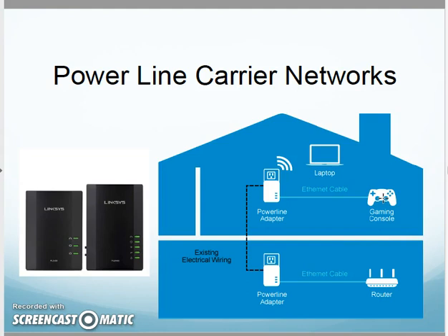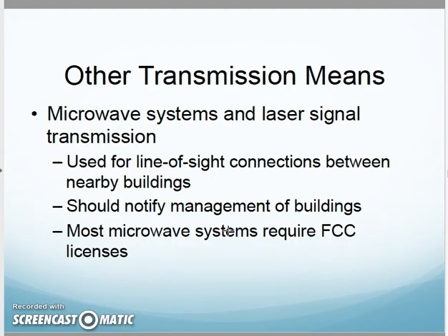And that's basically broadband over power line, BPL. That was something that was brought out as a technology, did not get widely deployed for ISP connection due to interference with certain radio frequencies that were being used, but has adopted little uses like this for homes. And I know people that successfully use it in their home to extend their network. It does work. They also mention in here microwave.